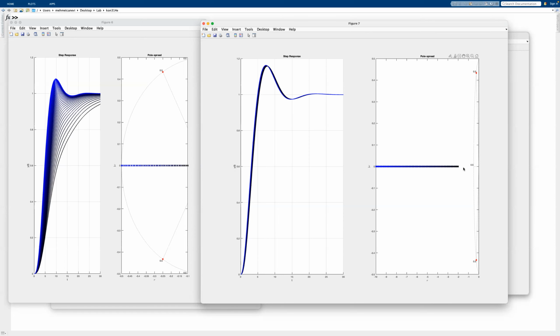And how far the pole should be is usually set like 5 times or 6 times away from the real value of our dominant one. So if the real value of our dominant poles is -1, you should be at least at -5, -6. -10 is even better. And from that on, it doesn't matter, because compared to each other, their relative speed is not that important, or their effect will be minimal, and we could use this.